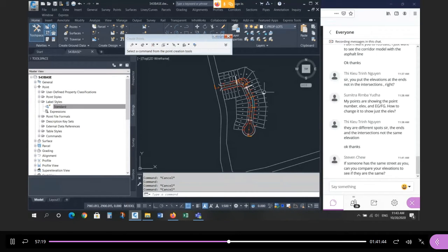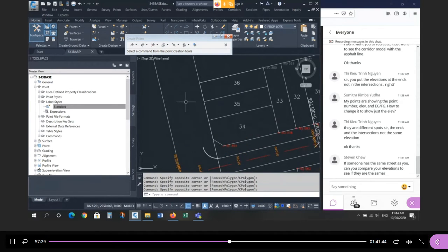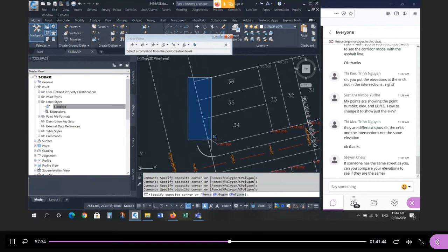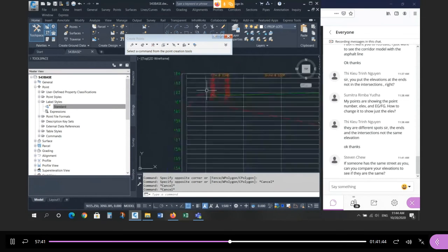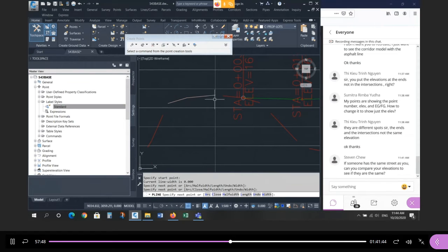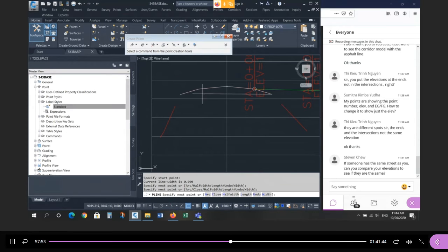The only exception to this technique, elevations from surface, are these 4 points here, or 6 points. How do you get the front lot corner here? What we're going to do is assume that because this is a proposed subdivision, we're going to propose an elevation here that's comparable to if this rural road was urbanized. So what it looks like, if we go to the profile, just for reference, let me just draw this, from the center to the edge of asphalt to the shoulder.